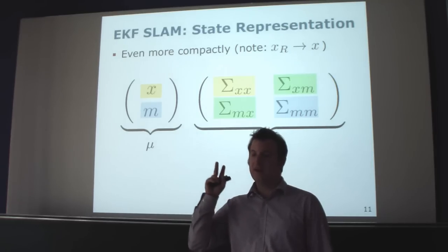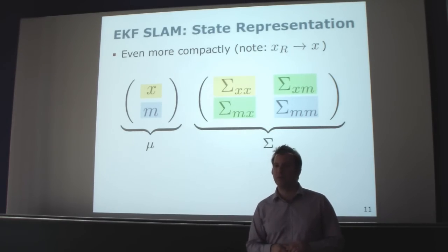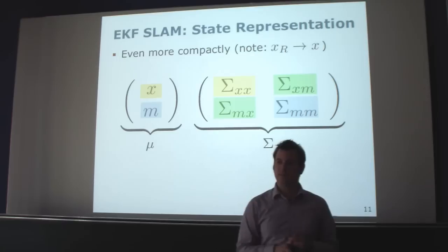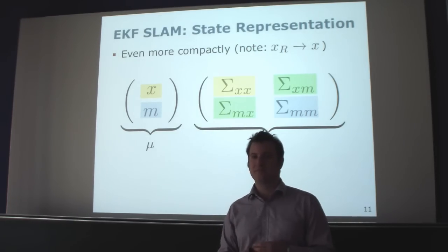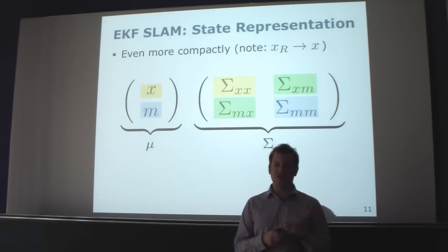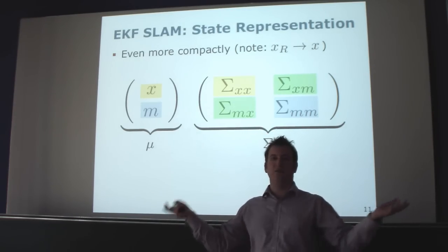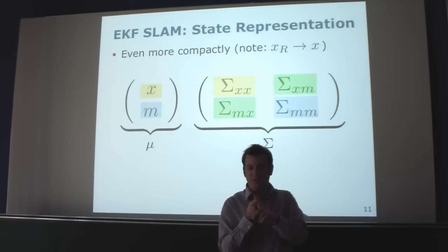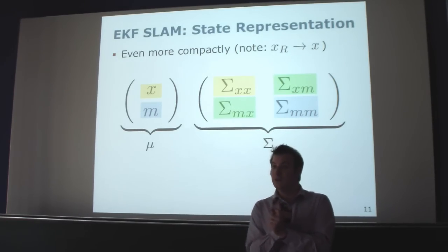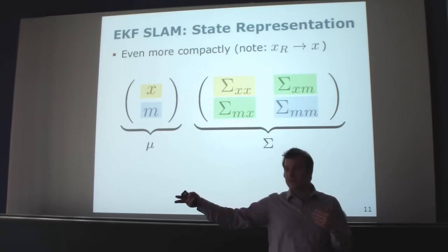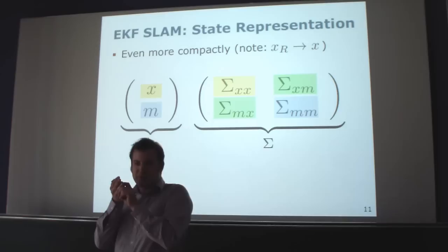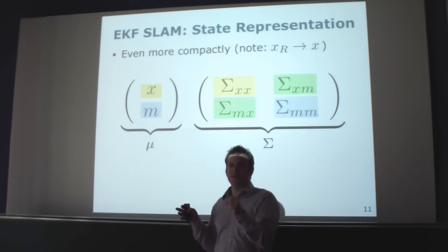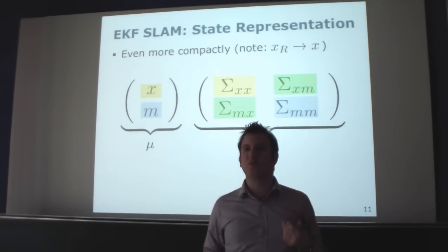Okay, so what are the key steps in our EKF if you want to use it for the SLAM problem? So what's the first thing we need to do? Initialize. Yeah, of course. We need to initialize it first. That's completely fine. So we need to initialize x and theta. Once we have done that, we get our observations and our commands. What do we do? First step. Prediction. First thing, the prediction. What we then need to do is compute the predicted measurements. So what are we expected to observe? And we need to take our measurement and compare those two, which also involves the data association. For the moment we assume that we know the data association. And then we do the update step. And then we continue this process.